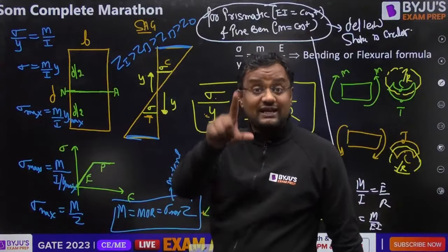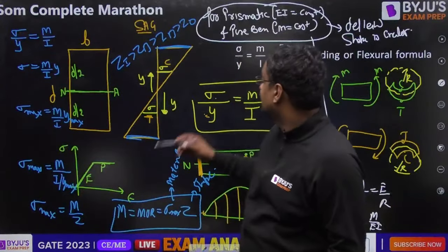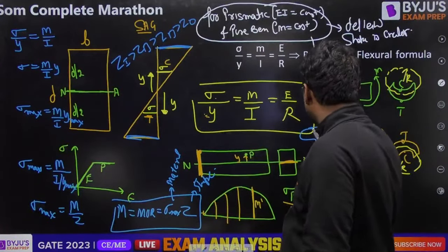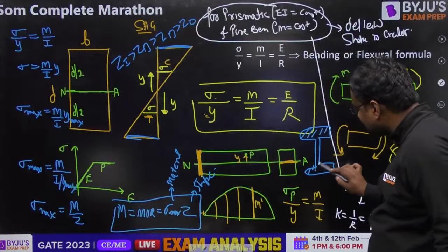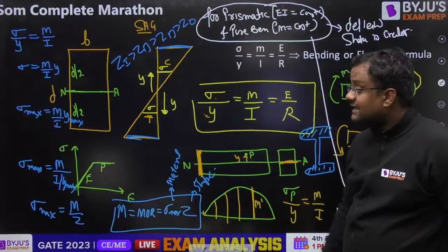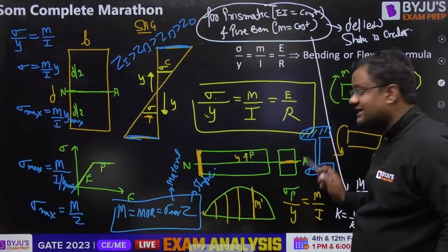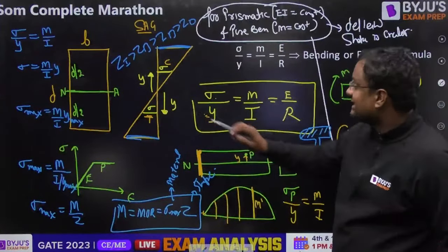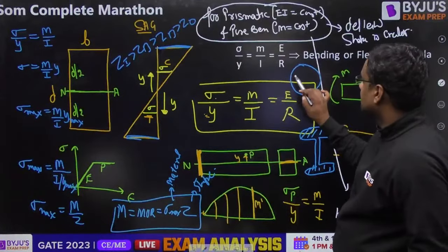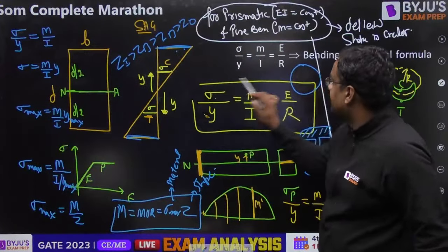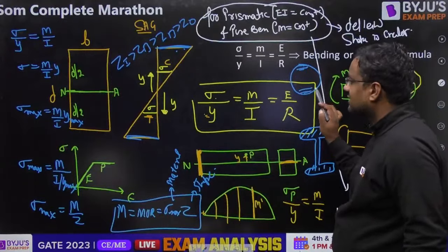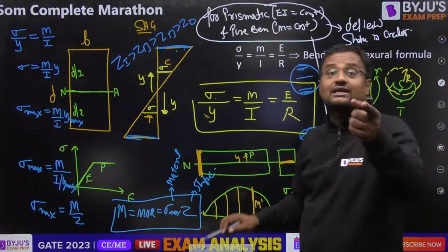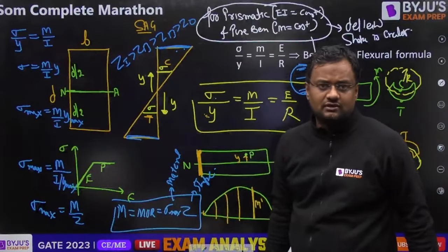And I section is very good in bending, the reason being that the area is more where bending stresses are more. Bending stresses are more at top and bottom, and there the area is more. Good design for bending. For shear we'll see it is poor. And circle is the poorest section because where the bending stresses are more, at top and bottom, the area is less, useless. And where stresses are less, at the neutral axis, the area is more. So circle is poor in bending. We'll see it is good in shear.